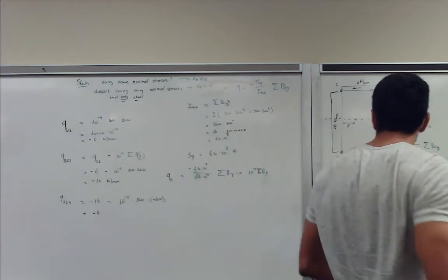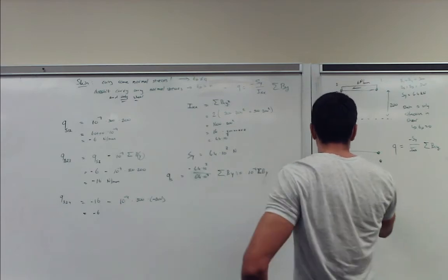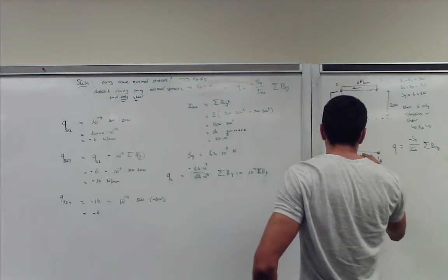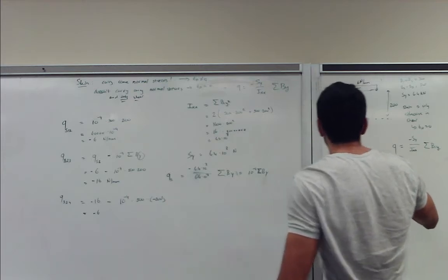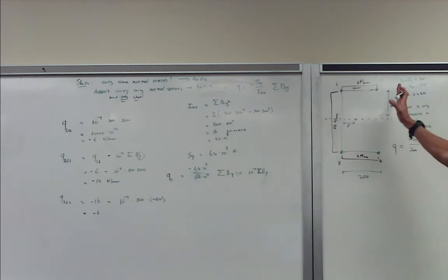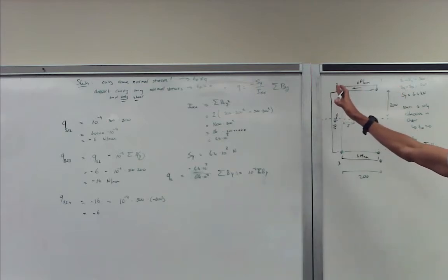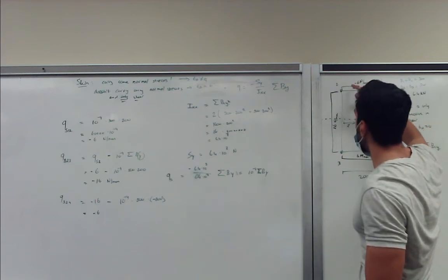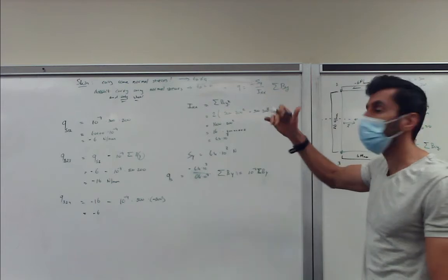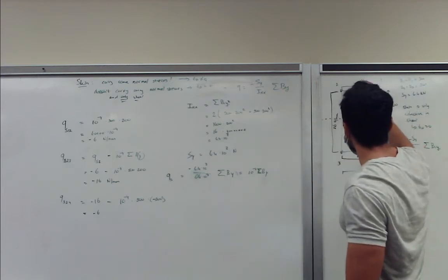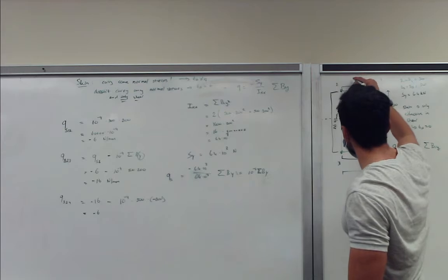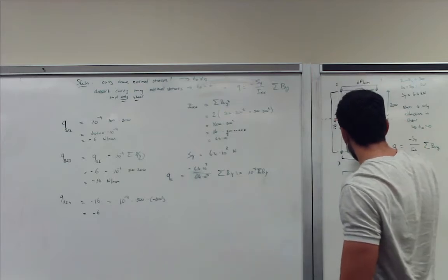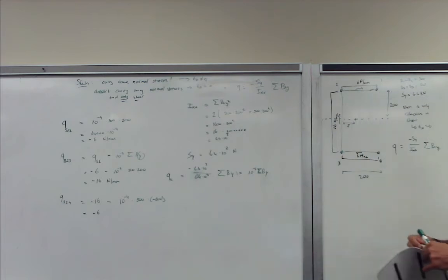So if you do it again, here we get 6 Newton millimeter. And again, what we stated earlier, we assumed it will go from 1 to 2. We got negative 6. So basically what that means is that our assumption for 1 to 2 is opposite. So if we would redraw it like this, it will be just 6. Let's do that. So it means that our shear flow went opposite than what we assumed. That's the only thing the negative shear flow number means.